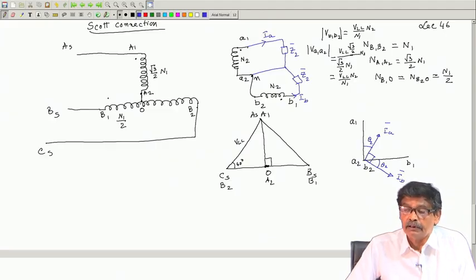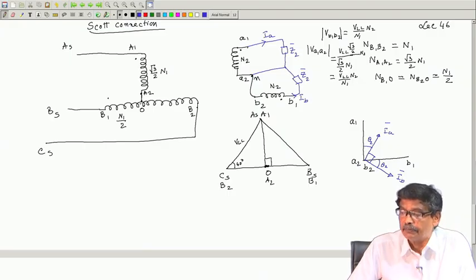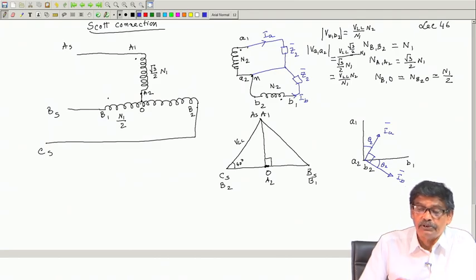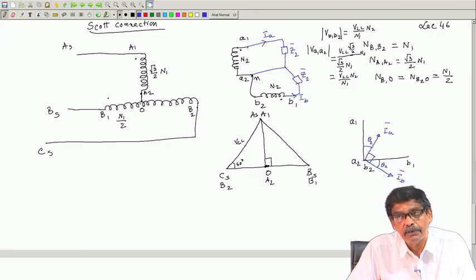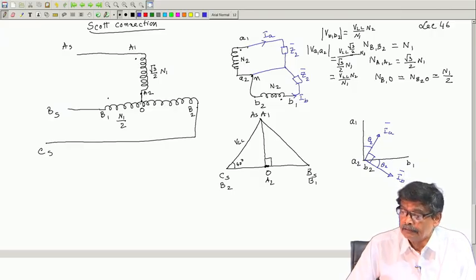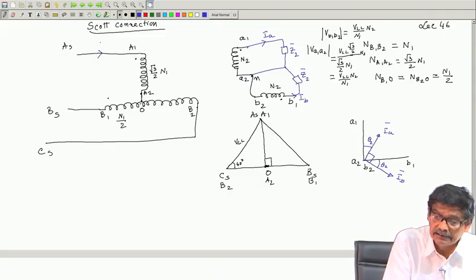Now, the question is, you have been able to transform a balanced three phase voltage to a balanced two phase voltage. Now, if I want to examine what will happen to the currents on the three phase side, will it also remain balanced or not? The answer we will soon see is yes, and how it is to be calculated. Therefore, I know I A, what will be my I AS, that I want to find out, what is my I BS and what is my I CS.